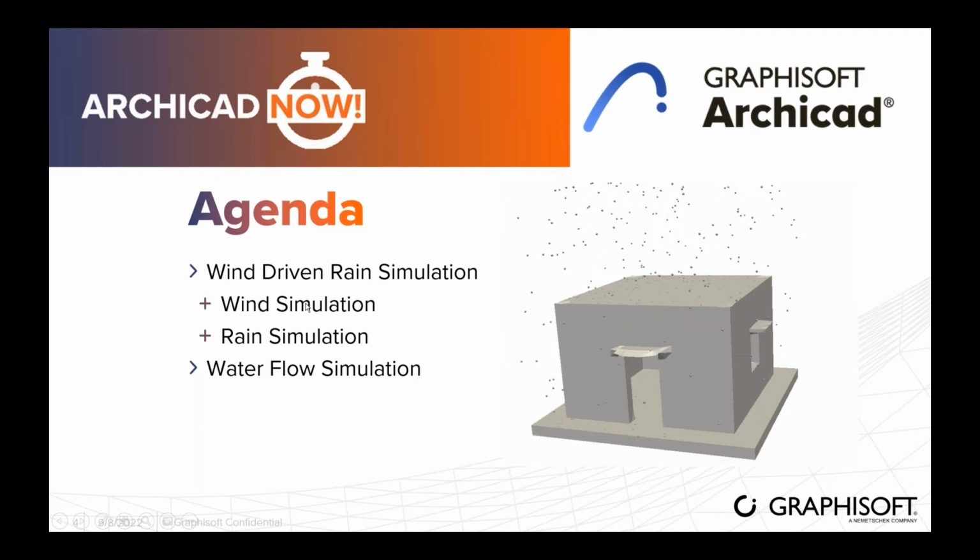But during the first simulation, we are not going to show the water flow, because if we do the water flow simulation, once the droplets or the rain hit the building, it will consume huge resources from the computer, and to perform such a simulation, it will take even weeks, even for a smaller building. So in order to simplify that, we are just going to do a wind-driven simulation, seeing where exactly the droplets fall on the building based on the wind around the building. Once it hits the building, the simulation stops there. It's not going to flow anywhere else.